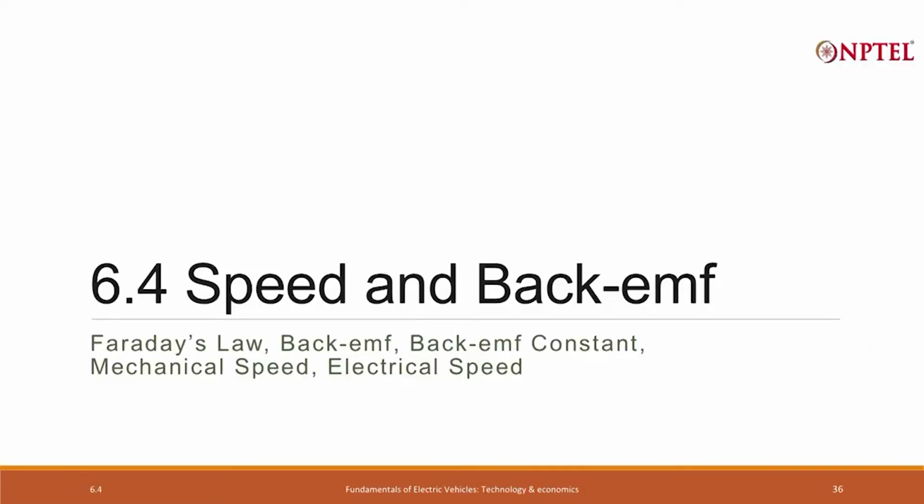So, what we just now discussed is what I have written here, and this equivalent circuit is very simple. The difference between the voltage and the back EMF is what will drive a current, and the drop, ohmic drop we call it, because it follows Ohm's law, I into R. The ohmic drop will be equal to the difference between the applied voltage and the back EMF. Is this clear? We are talking so far only about the PMDC motor.